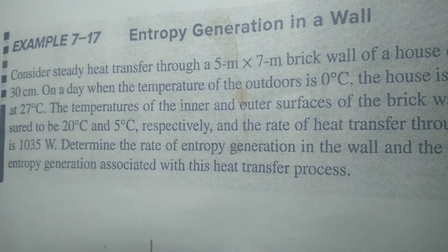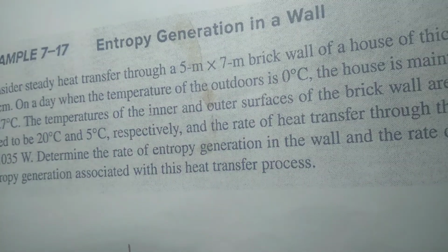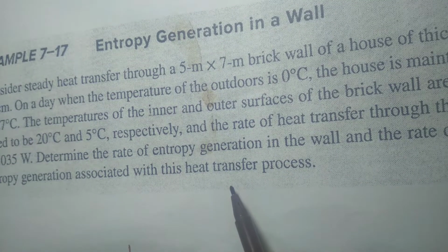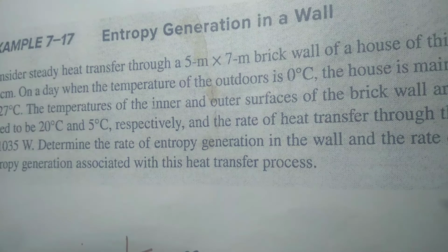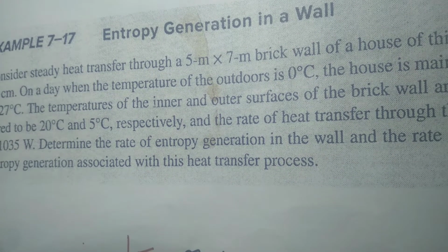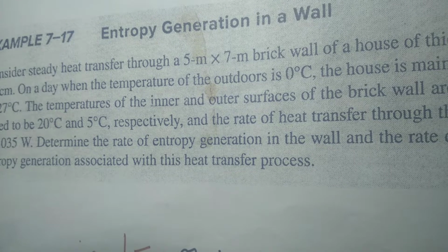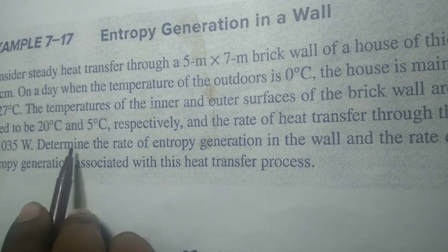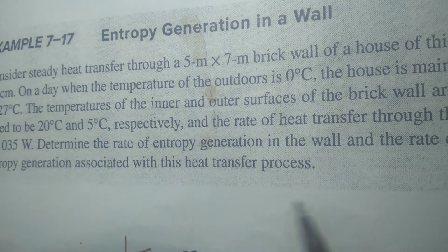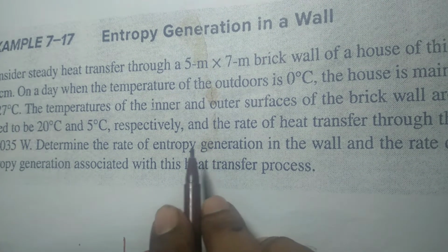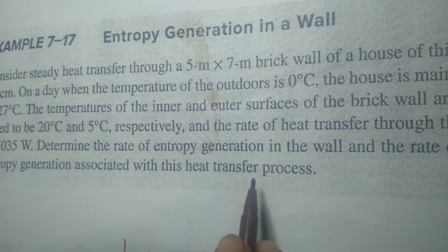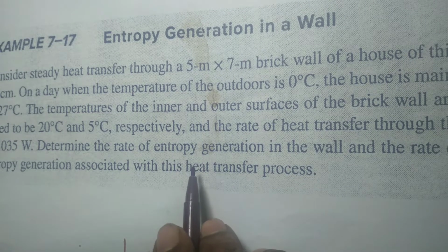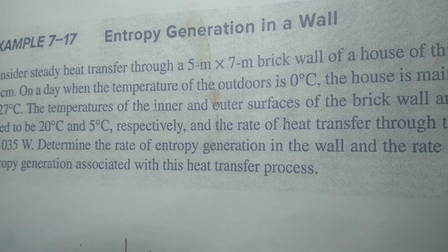Determine the rate of entropy generation in the wall and the rate of total entropy generation associated with this heat transfer process. Entropy is generated only during an irreversible process. Of course, an irreversible process takes place when the heat transfer takes place through a finite temperature difference. In all these cases, there is a finite temperature difference, so there will definitely be some entropy generation during the process. That's what we are required to find out in this question.